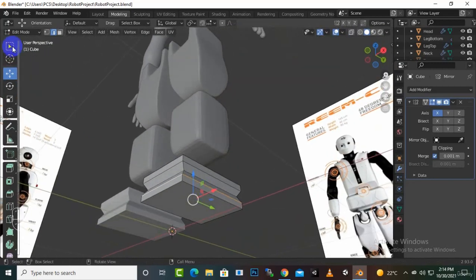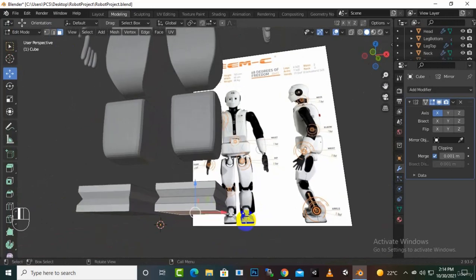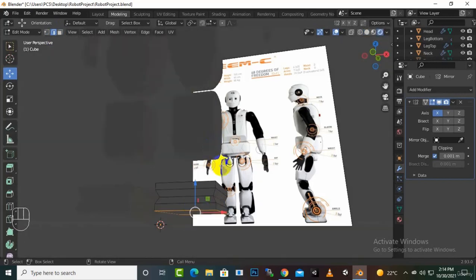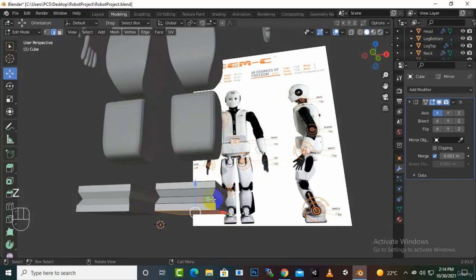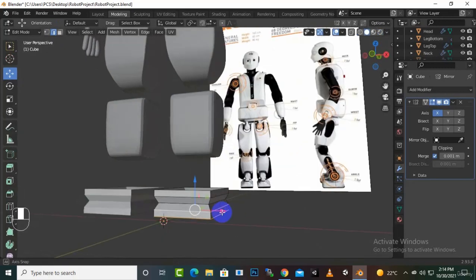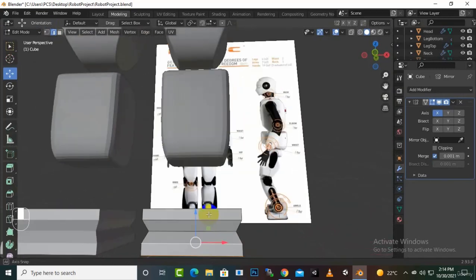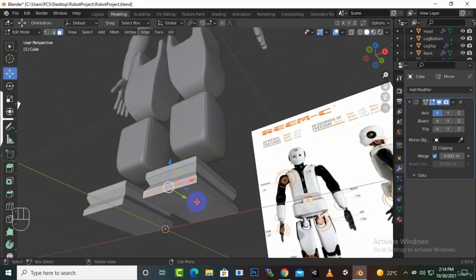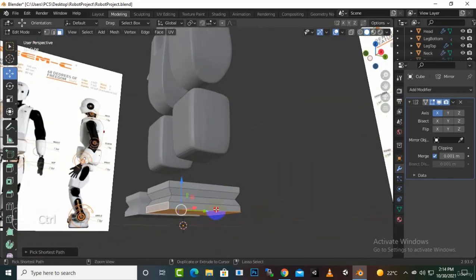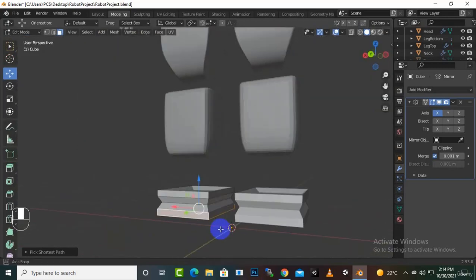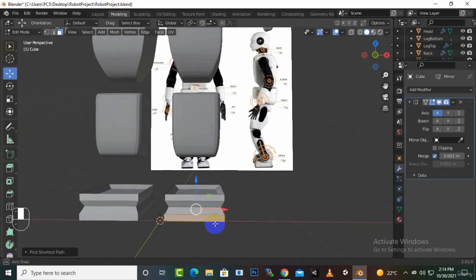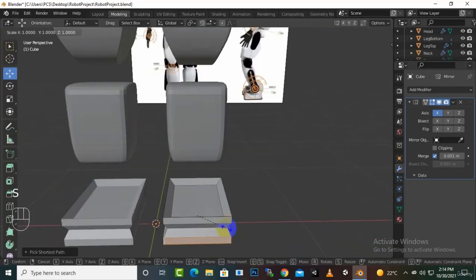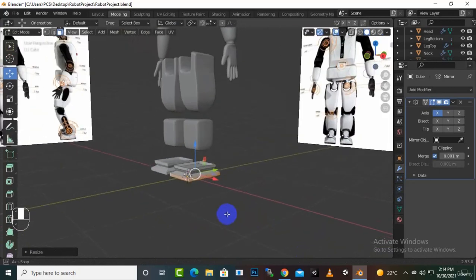And then we'll just select this last section, and then this loop with the alt. I will go to solid view, alt shift alt click. Okay, so now these two are selected, but you can see that this polygon we want to select, so let's select this one. With control we can select this one as well, so let's select this one as well, and now we will press S to scale it a little bit like this. So this is very nice feet.